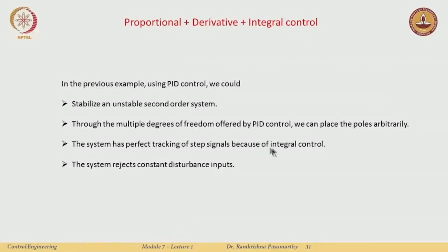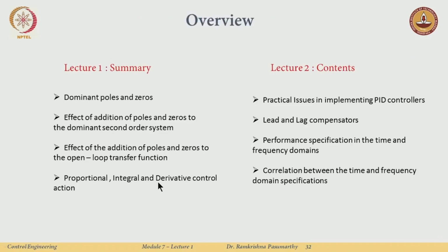The system has perfect tracking because of the integral control, and integral control also rejects constant disturbance inputs.